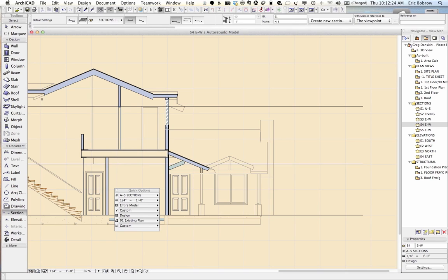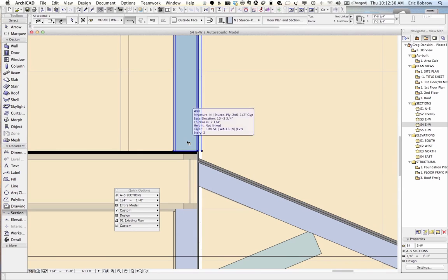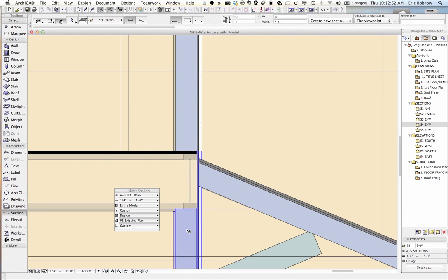will give you a good reference that you can set your windows and doors to, and even if your wall was to move down, you wouldn't have to worry about that because you're just setting the window or door height relative to the story. Now in this case, you can see that we got a perfectly good result by keeping the wall on top of, at the zero for that, let's say the top of the structural floor here, and we took the lower wall up, and it did just fine.